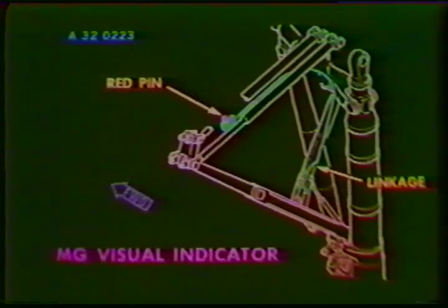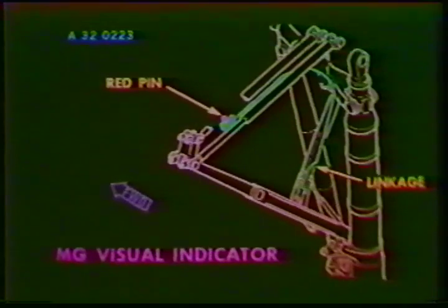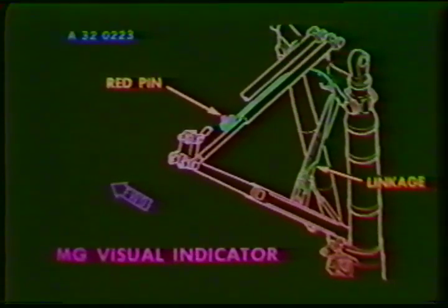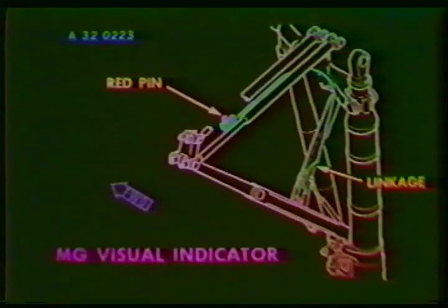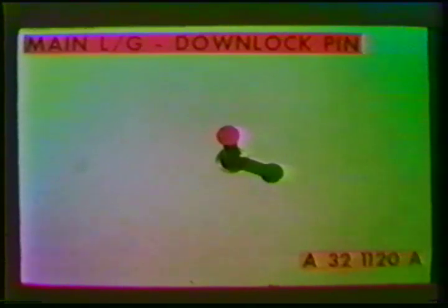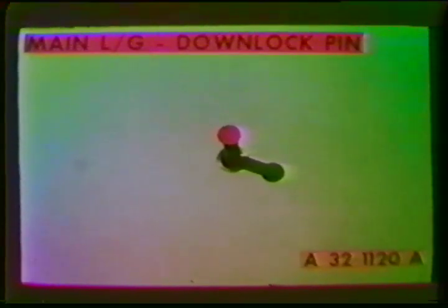If the electrical indication systems are not available, or if you desire a visual confirmation of a downlock condition on the main landing gear, mechanical pop-up indicators on the wing upper surface can be viewed from a cabin window. Pop-ups extended means geared down and locked.